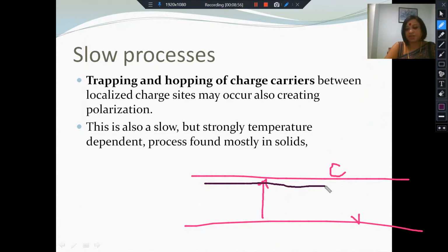energy levels which are vacant. So there might be positions in the lattice which require an energy which is less than the conduction band but very close to it, pretty far away from the valence band, and these are called trap levels. When they're very close to the conduction band, they're called shallow traps. When they are closer to the valence band, they're called deeper traps. When I say shallow or deep, it is not about the height in the physical sense, but about the difference in energy between this energy level and the energy level in the conduction band.